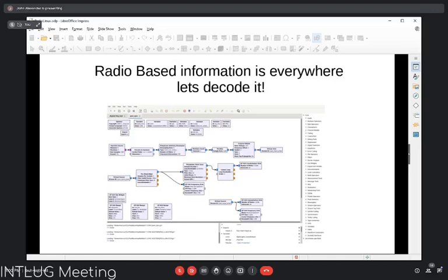But as you can see, you can just load that. It's called GRC, GNU Radio Companion. That tunes FM radio. That was probably GQRX, I think. It just had the heat map on there and the waterfall. That's probably GQRX. That's definitely free. Also SDRAngel, which does a lot more. That's also an open source application. So it very much depends on what you want to do.